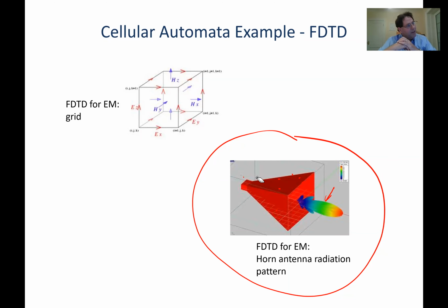If cost is no object and speed is everything, that'd be a reasonable thing to do. Obviously, it becomes an expensive system if every time your problem size doubles, you have to buy twice as many chips. So it basically trades cost for time. And there is a company that does exactly this with FPGAs for finite difference time domain electromagnetics. So this particular example is not a very hypothetical one at all. And they do use multiple FPGAs to get higher throughput, exactly what Madi is suggesting.